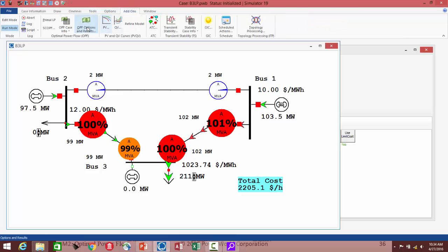Now if I solve the OPF, what I see, instead of having all of the overload appear on one transmission line and the other one being a binding limit, is that they're both exceeding their limits. This one is settled at a breakpoint, at the 5% breakpoint, and then the rest of it comes here. And the penalty cost is lower, and the LMP at that bus is lower. So you can see that, and then the different values would be reflected.